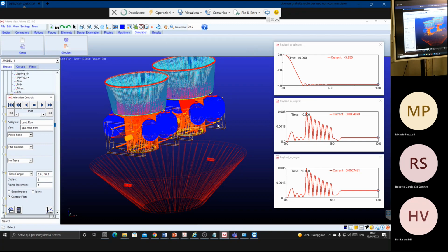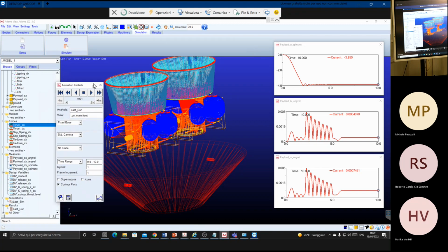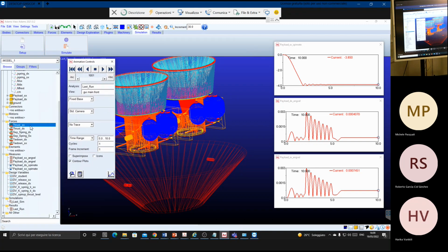In this case, for example, I provided two thrust forces on left and right. So these are two forces which I applied. You can think of it as two thrusters which are attached to the payload adapter, which provide this rotating motion. Again, this is a way to model it. This is the closest to reality, but you can also provide a torque directly instead of two opposite forces.